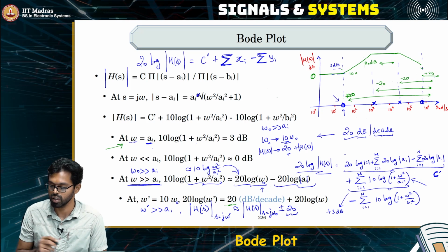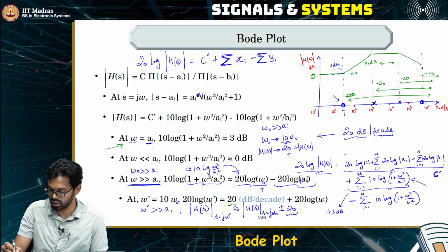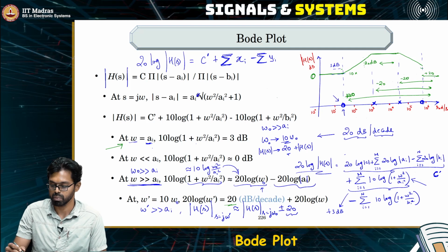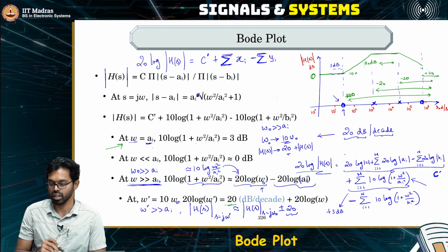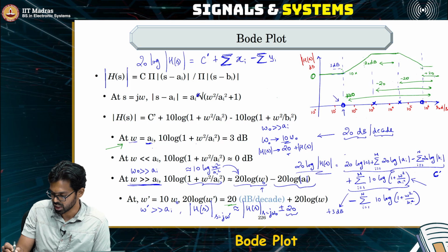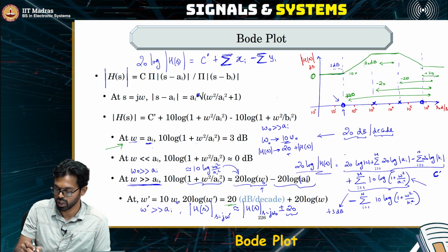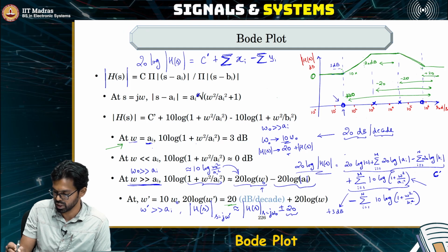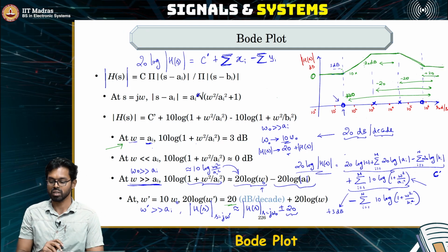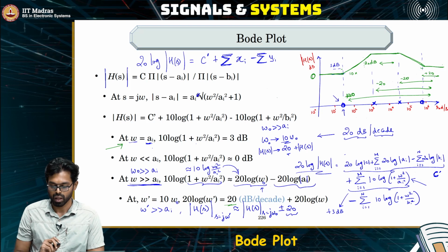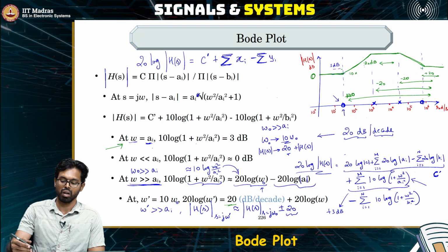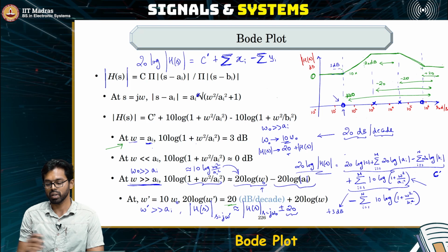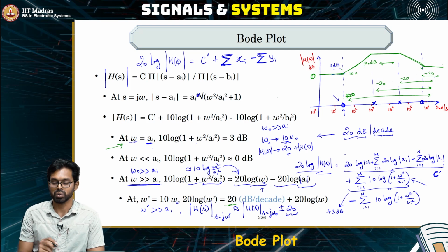The slope is negative. Now you have hit a 0. So plus 20, minus 20, minus 20, plus 20. Effectively it is 0 again, so it's a straight line. So the Bode plot in the most approximate manner is drawn like this, where you just increment a plus 20 wherever you see 0, and you just decrement a 20 dB wherever you see a pole.